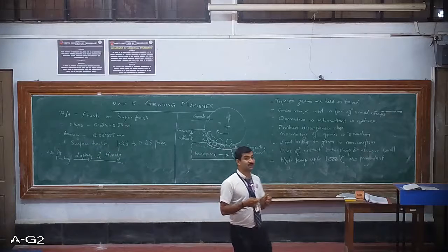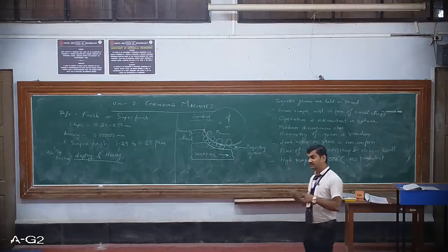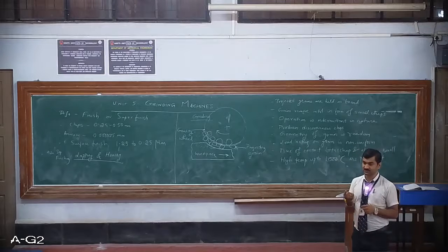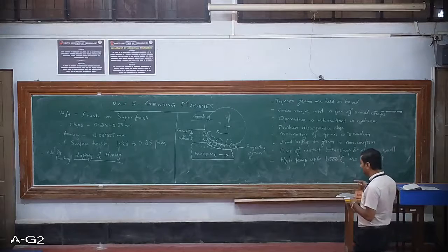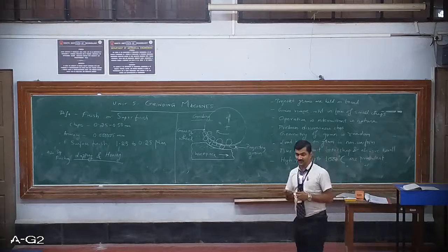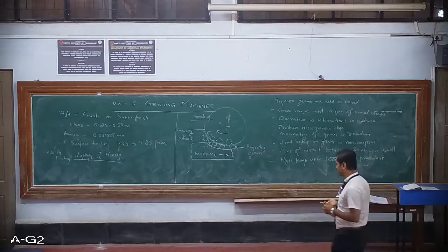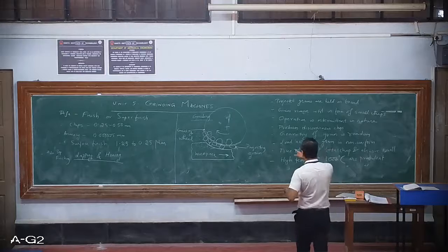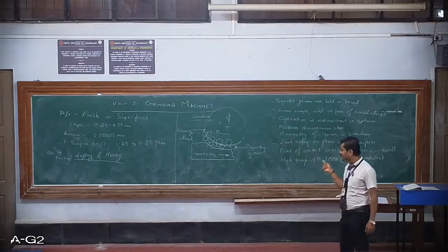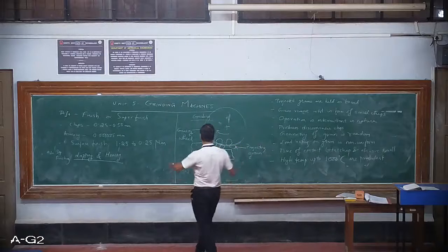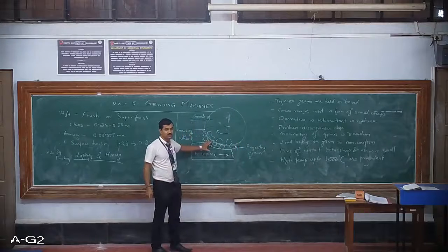There is a rubbing action, friction is generated, and the abrasive particles, which are sharp in nature, prick the material. They prick the material and remove it in the form of fine chips that are thrown away. Please remember, the wheel is rotating at a high speed, the work is fed against it, so it is clockwise rotation and the work is fed against the wheel.